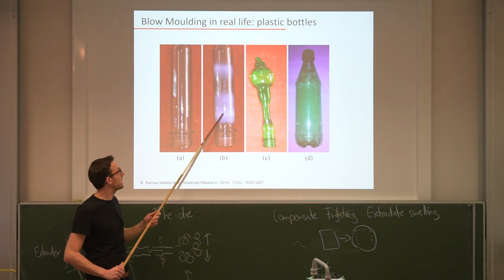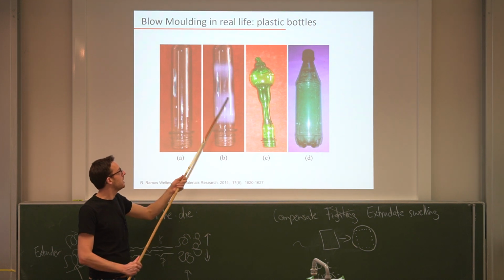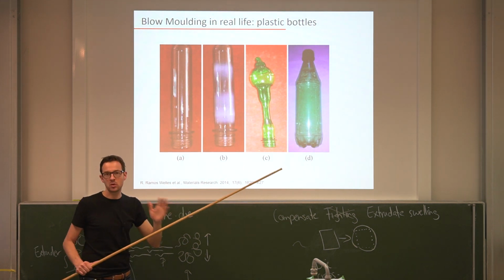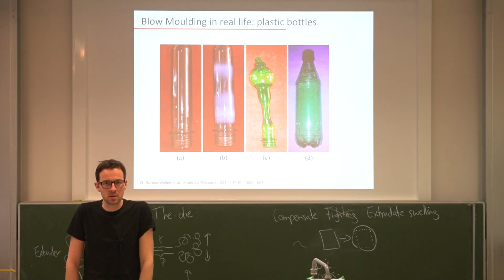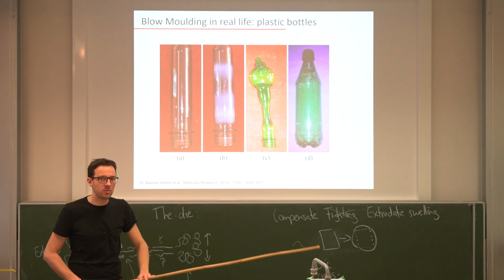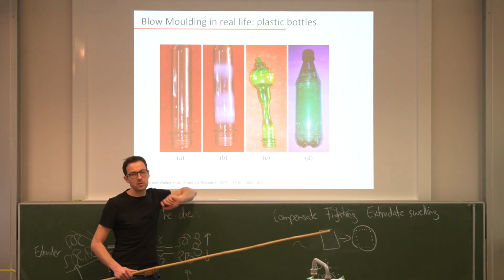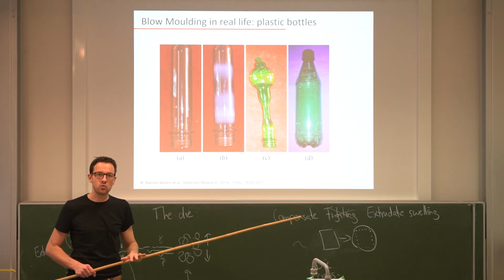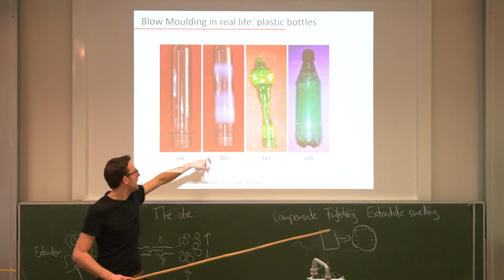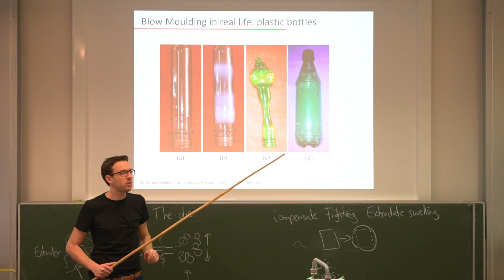And when you have defects in your preform, so you see here, apparently the material started to crystallize. Why do I know that it's crystallized? Think about it for yourself a little bit. Little hint related to the color. So we see it became opaque, and opaque means that there must be two different refractive indices, and this is a telltale sign that it can have crystallized.